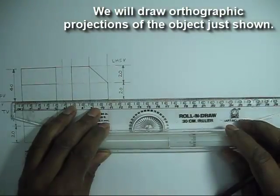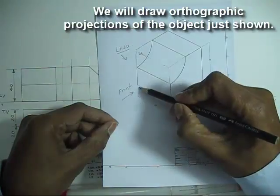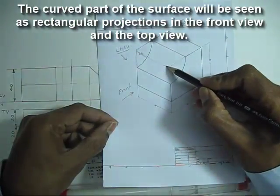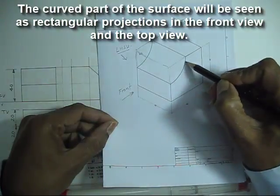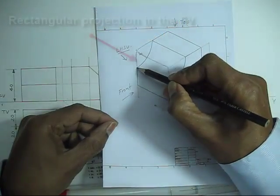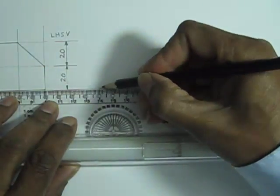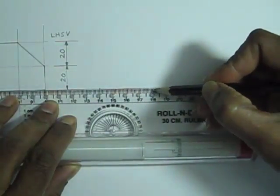So now we will draw the orthographic projections of the cube which has been cut by a curved surface. This part will be seen in the front view and the curved part will be seen as a projected rectangle. So in the front view we will see two rectangles. We draw the front view first.